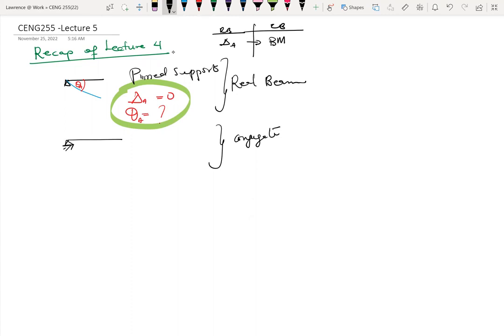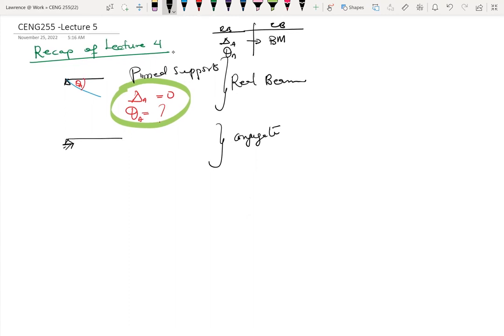We also know that the slope at any point is the same as finding the shear at the conjugate beam if you're comparing the two. All right. So again, we also need to devise a case whereby this reaction VA and then the moment MA, so let me say MA prime and VA prime because it's a conjugate beam.